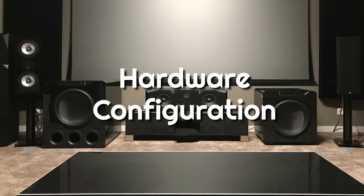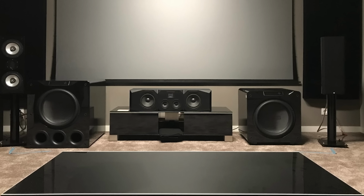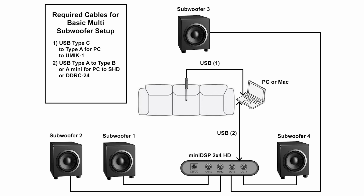Subwoofer placement is driven by the number of subwoofers in your system, listening room configuration, and aesthetics. In general, spatial diversity is preferred. You'll need to temporarily connect the audio output to the miniDSP using USB. REW test signals generated in your computer will be used for frequency response testing. The direct USB connection approach is ideal because we are calibrating the subwoofers as a single virtual subwoofer, and then later connecting the miniDSP to the AVR through analog cables.